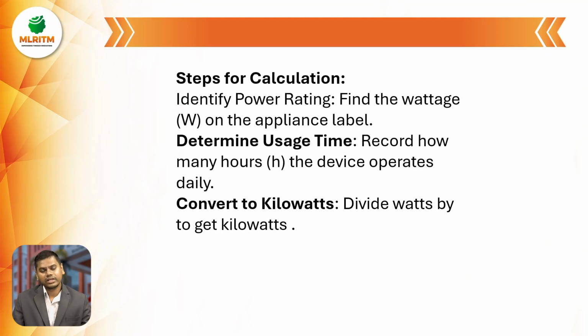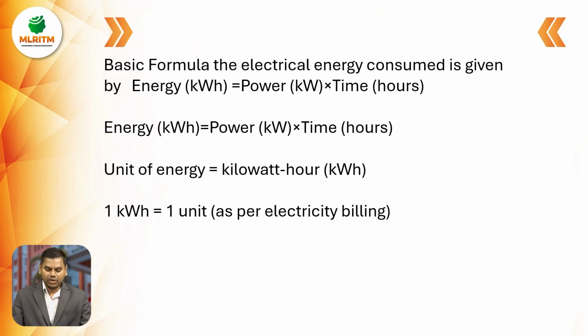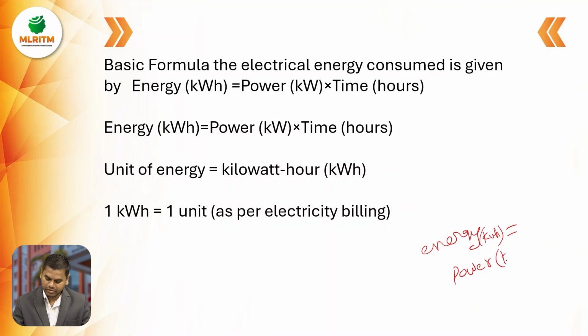There are many steps, but here I'm taking only a few: identify power rating, determine usage time, and convert to kilowatts. The basic formula of electrical energy consumed is: energy in kWh, kilowatt hours, is equal to power in kW multiplied by time. As I said before, the time is taken only in hours.